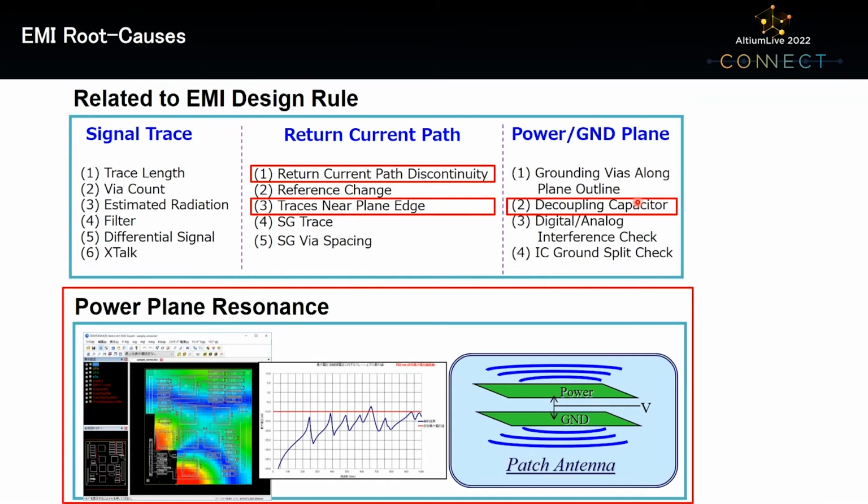Today, I explained the important design rules: return current past discontinuity, traces near plane edge, and decoupling capacitor out of the 15 EMI rules, and the basic knowledge and verification result of power plane resonance analysis. Now, EMI design rule check and plane resonance analysis are available in the Altium Designer extension. From now on, Yoshi Fukawa will start the demonstration of the EMI Stream extension. So Yoshi, take it away.